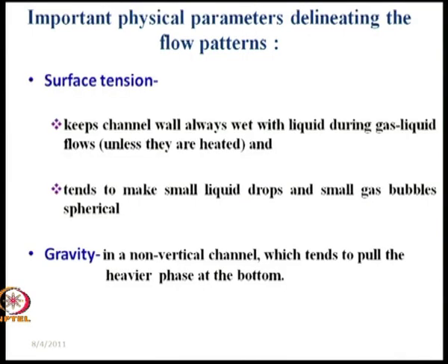So, we find that the basic factors which delineate the different flow patterns are, number one, surface tension. It tends to make small liquid drops and small gas bubbles spherical. And the other important thing is, particularly for gas liquid or vapor liquid flows, there will always be a tendency of the liquid phase to wet the pipe wall.